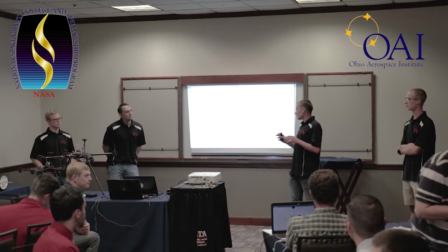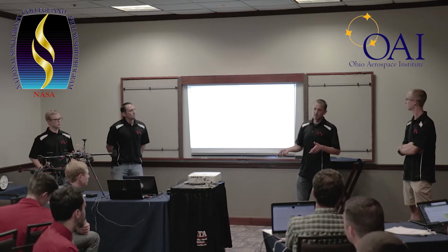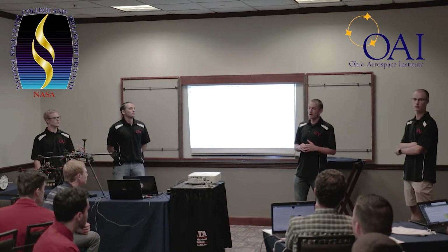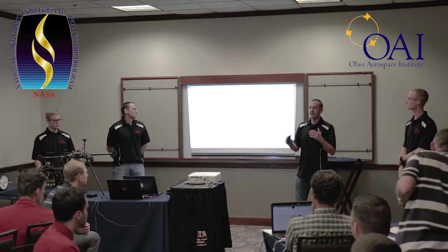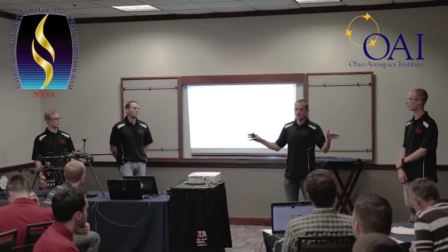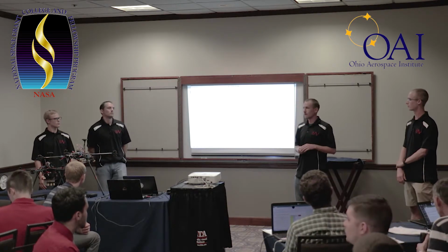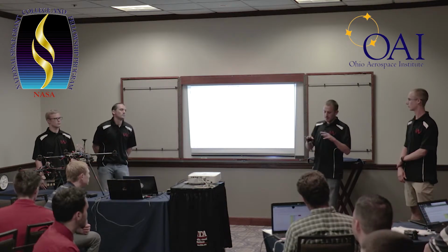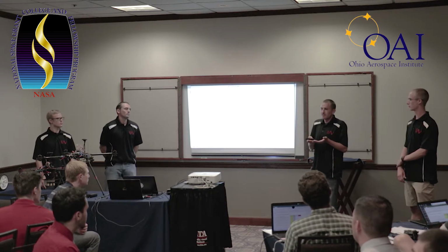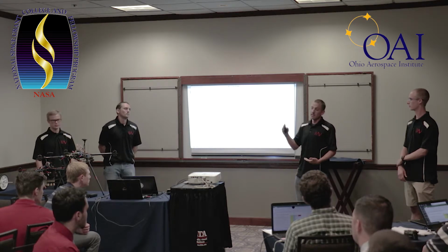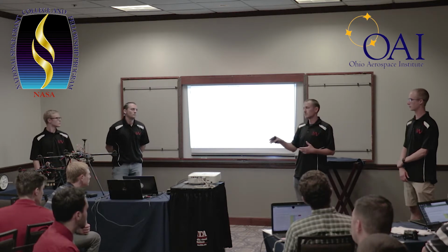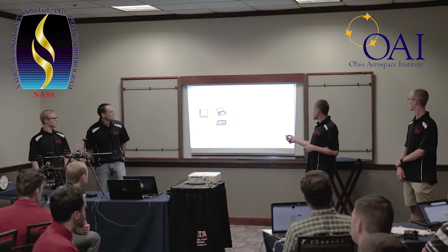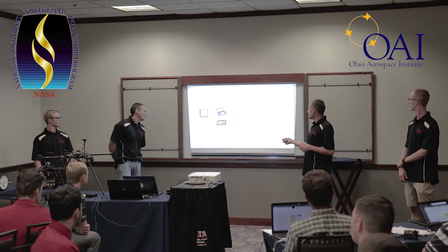And that is the basis for a lot of this. So it's huge on platform flexibility. Different programming languages are supported through ROS. It takes care of all the driver integration, message passing, distributed networks, so you can have multiple of these things in the air at the same time, which we've done before. And we created this simple ground station interface that really doesn't rely on the link, so the link can die. All this stuff mostly runs on the onboard computer on there. So as you can see in the picture right here, we have this is ground control.